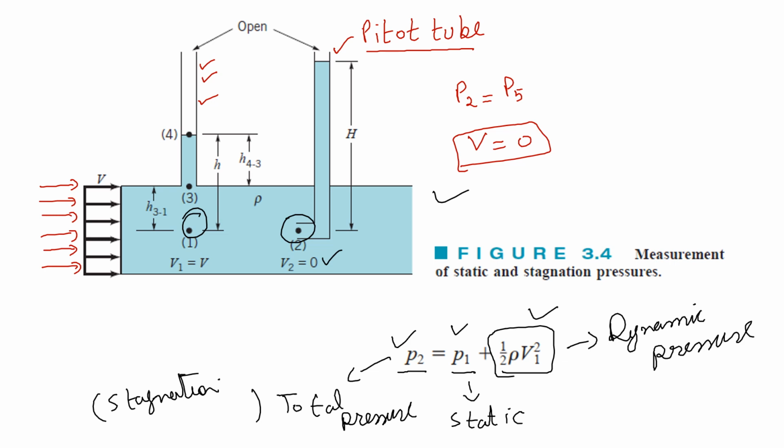As you can see, the total pressure is at point 2 where the fluid is at rest, and bringing the fluid to rest requires a certain amount of force that the fluid will apply on that surface. So here we have used a pitot static tube for that purpose, and in this tube overall the fluid is at rest. So at point 2 we have the total pressure that resulted when we brought the fluid of a certain velocity to rest at this point 2.